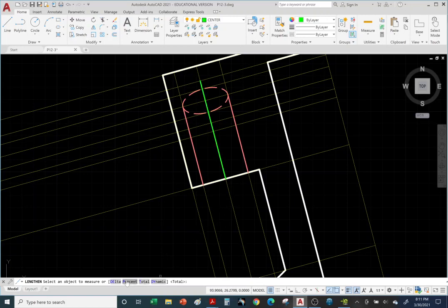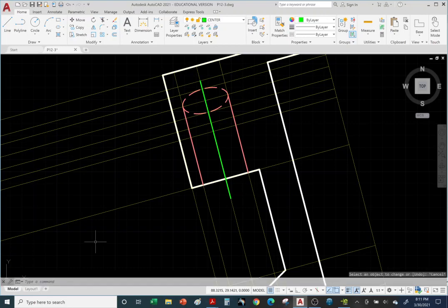So I'm going to click on the word percent. I'm going to increase it by, so I'm going to go 120. So add 20%. So I'm going to go 120%. See what we get. If not, we can always redo it. Enter. I'm going to hover over this portion. See, it's going to increase it by 20% for a total of 120%. Click. There it is. It extends it. And we're done. Hit escape.